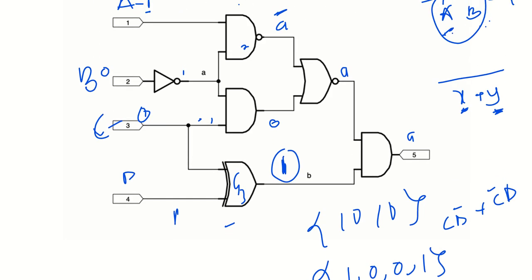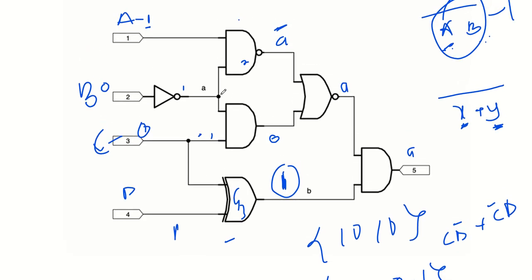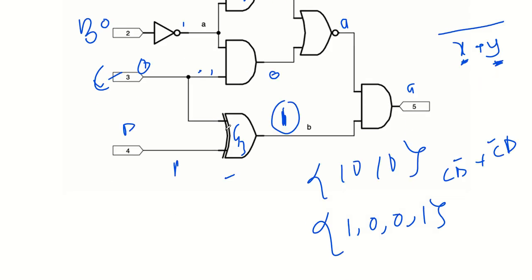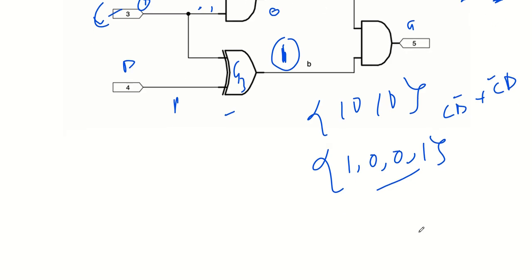You realize that in the very first one, we had a bit of a problem determining what A should be when we were propagating backwards. But the second one is more sure, so I believe that we can go with the second one. However, let's still try the Boolean difference method to check if we'll get the same answers.